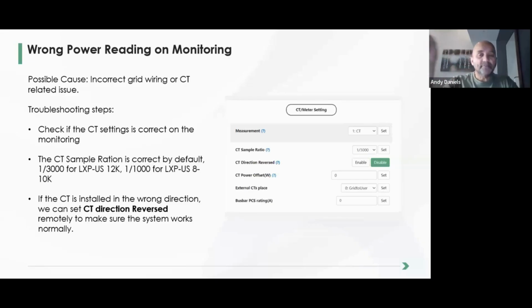You then take your clamp meter, you clamp the hot 1 or hot 2, and you verify that in fact the CT, if it says it's exporting power, that it is exporting power. And if that's the case, then it's obviously an error or a marginal error in the reading. Then you can offset the CT. So for instance, if the CT is exporting, say, 100 watts, and you set this value to a negative 100 watts, it will prevent 100 watts from going out. The converse, however, is also true. If you have a CT that is accurate and it's on 0, and you want to trickle in a little bit of power, you can also set it to a negative value.